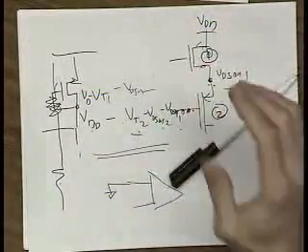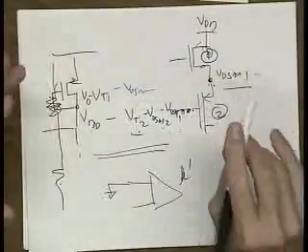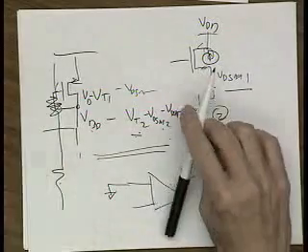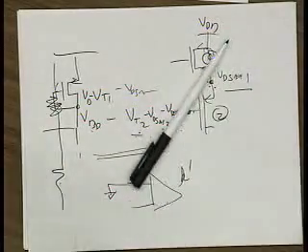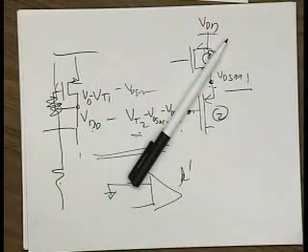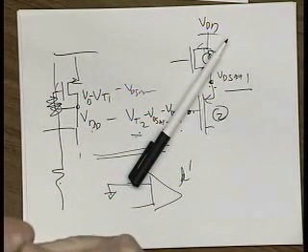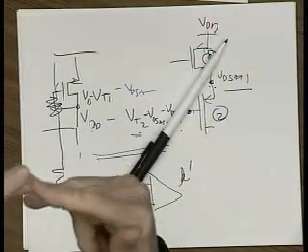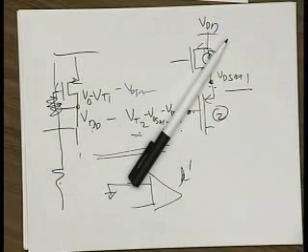Where does that reference current come from? It comes from a lot of things. Sometimes what you can do is bring that external. There'll be one reference current on your chip that somebody sets up with a precision resistor. In your data sheet you'll say, put a 1% valued resistor between this point and ground, of this value, 10k ohms. So you rely on that external 1% resistor, which costs 10 cents. Say, well, 10 cents doesn't matter too much. Well, it might matter a lot, actually.